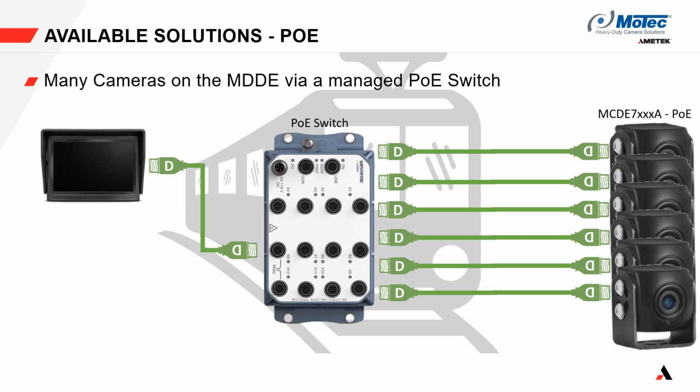However, in industries where the cables can get extremely long, like for example in the railway industry, base 100 T1 might no longer be sufficient to do the job. Additionally, these are longer, bigger vehicles that do many times feature a lot of cameras spread all around the machine. In this case, it is necessary to add a switch into the network because the monitor no longer provides a sufficient amount of interfaces for the cameras to connect to.